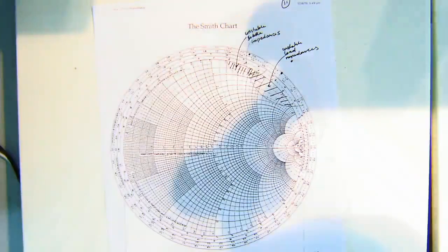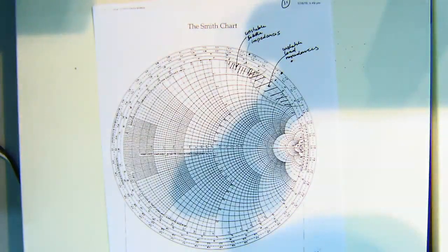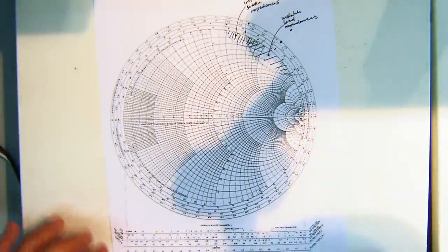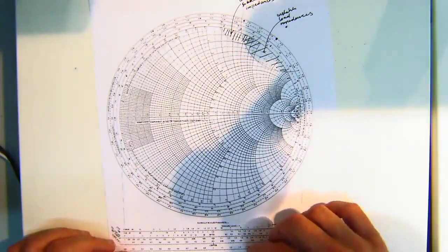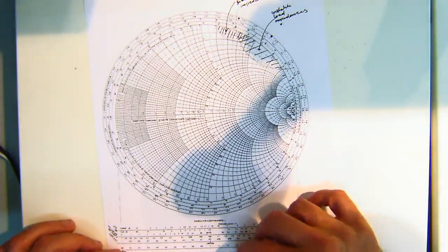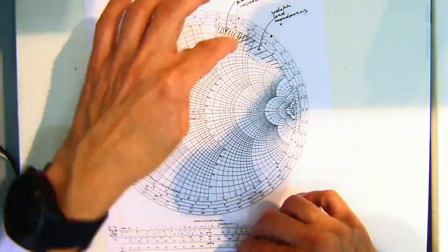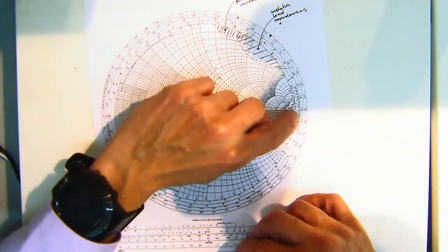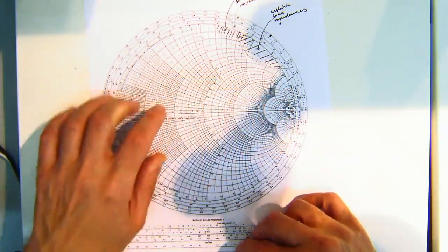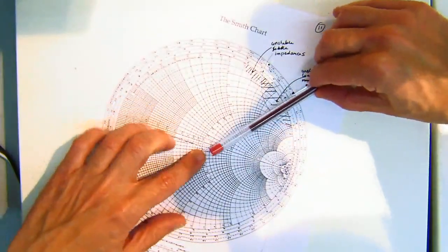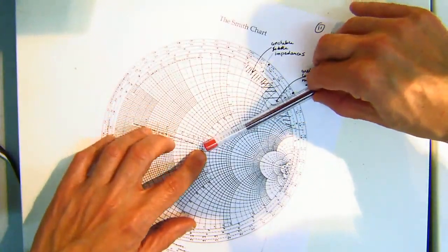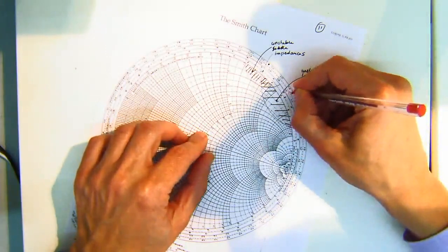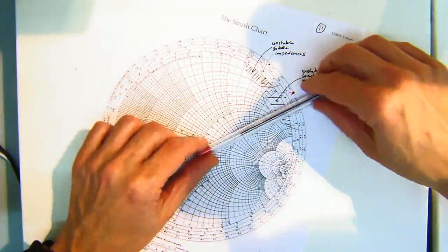I apologise because I didn't bring a ruler, but essentially I'm doing two things. I find 1.361 down here, so that gives me the length. I find where 47 degrees is, which is the angle of the reflection coefficient in degrees, and all I do is essentially do that. And that's where I've drawn the point. Neglect that other point. That was me making an initial mistake.